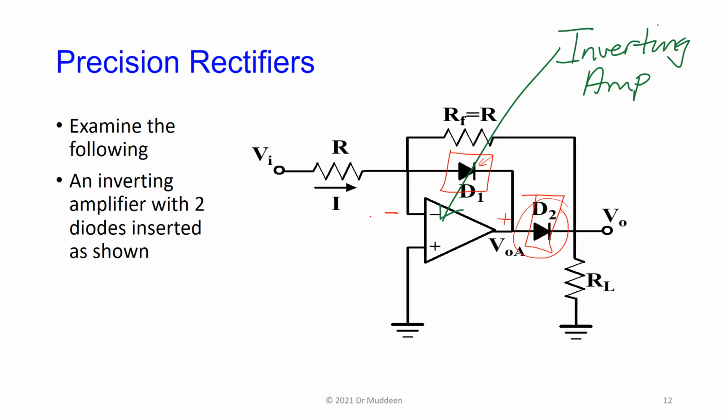And once it turns on, it means for a negative input, the output is going to respond here. When you put a positive input here, because it's an inverting amplifier, here goes negative. Negative will turn off this diode, but turn on this. And what the amplifier does, remember, the op-amp tries to make these two voltages equal. So it is trying to pull here to ground. Here's positive, it is pulling here to ground.